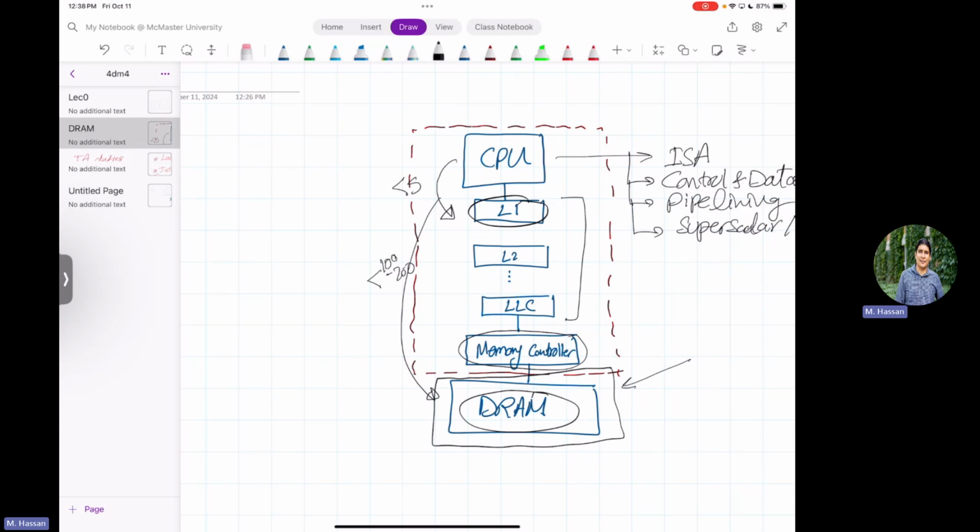All of your levels of caches, again, if you remember our cache lecture, we had boxes on the chip that tell you this is an L1, this is an L2, this is an L3. So it's all within the same CPU chip, manufactured by Intel or AMD or ARM, for example. ARM doesn't manufacture, but simply whoever is using ARM chips. Good. While DRAMs are in fact manufactured completely by different vendors.